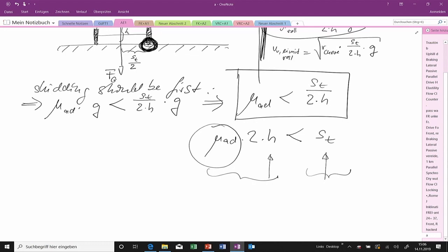You know, when I displace the mass and I release it, and then I let my hands off so that the pendulum can oscillate free, it will oscillate with a very specific frequency. Yeah? That frequency does not depend on my displacement, which I have introduced in the beginning. It's a system property. This frequency is a system property. It can be calculated from the spring rate and from the mass.